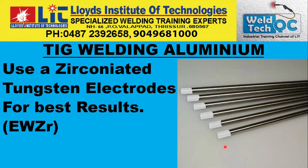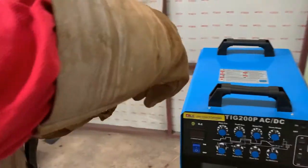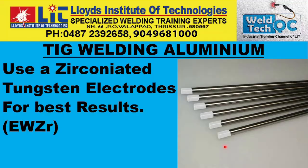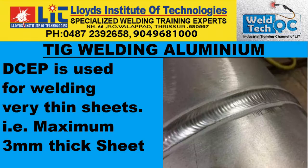And do not forget, you have to choose the right tungsten electrode for best results. It is the zirconiated tungsten electrode, EWZr. You have to prepare the electrode tip rounded for AC TIG welding. You can do it this way or directly this way also, but it is always better to get it rounded.